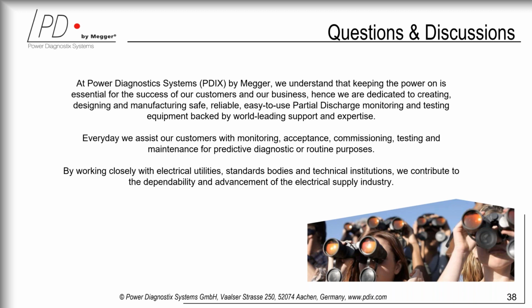So Marcus had touched on this a little bit before, and basically you can tell by the pulse shape analysis. As Marcus said, if you have PD from the bushing, it'll look a lot like the calibrating signal. You can also tell by testing at a bushing whether or not it's coming from that bushing.